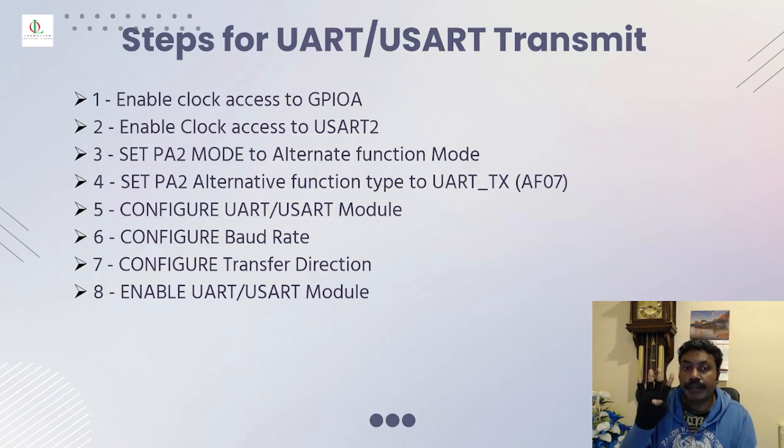So there are basically four port modes that you can set and configure. When you say PA2, what does that stand for? I'm sure most of you would know by now. It is nothing but port A and pin 2. So you've got to set port A and pin 2 to alternate function mode. I'll tell you why we are learning only PA2 today in the next slides.